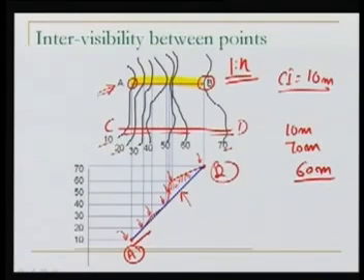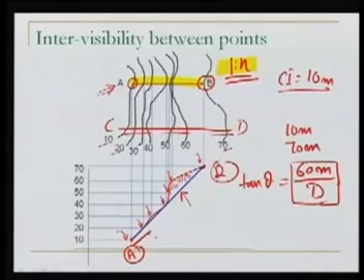We can measure this horizontal distance, convert it to this scale, and write this distance AB, whatever it is, let us say D. So, this gives us the slope of the line of sight, and this we can also write as tan theta. So, our theta angle is this.